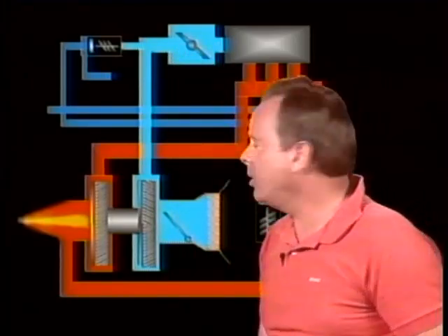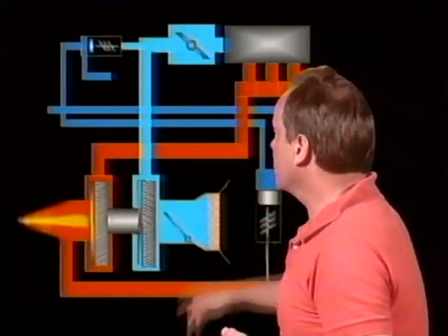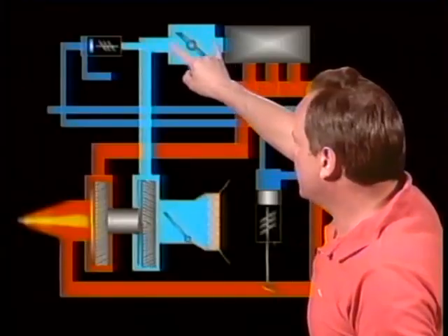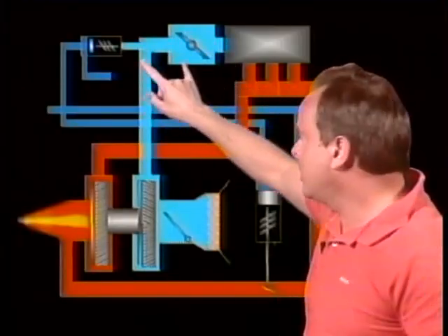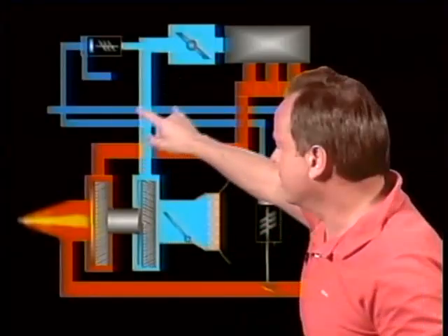This system, the pressure differential controller, also prevents you from having bootstrapping: the turbocharger going up and the turbocharger going down, and the whole engine picking up RPM and dropping off on RPM and manifold pressure, because it tends to stabilize since it maintains that 2-inch difference. So this differential pressure controller tends to eliminate bootstrapping. We'll talk more about that on a question later on.